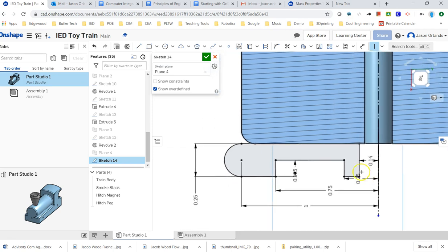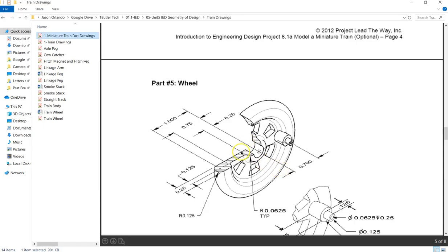So the last thing though is I've got to round off these edges. These were rounded edges back in here. And so I've got to scour and look around. I see this leader line. You know, leader lines are generally dimensioning arcs and circular features. That's an 1/8 of an inch radius. That's on the end. Well, that makes sense.